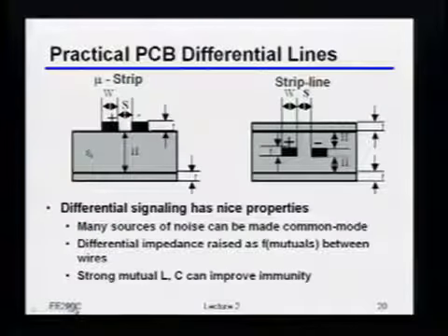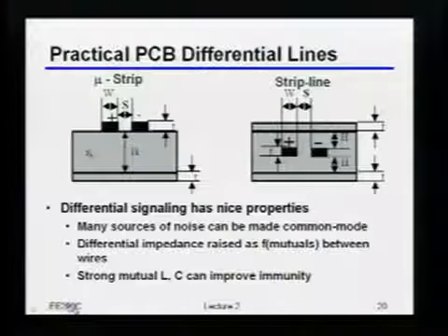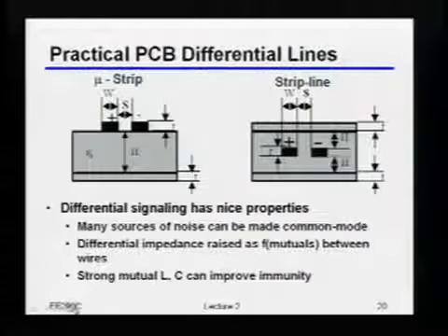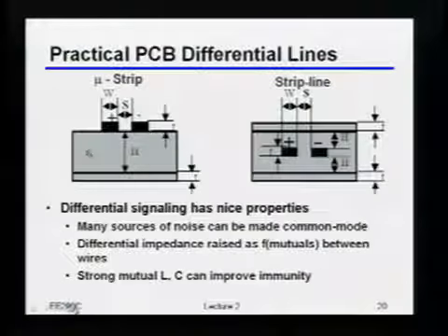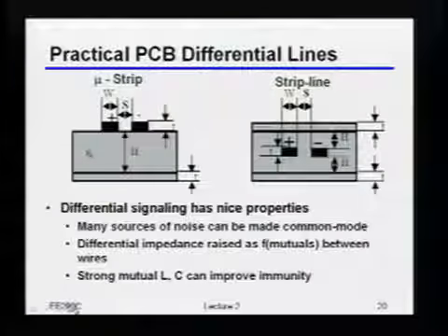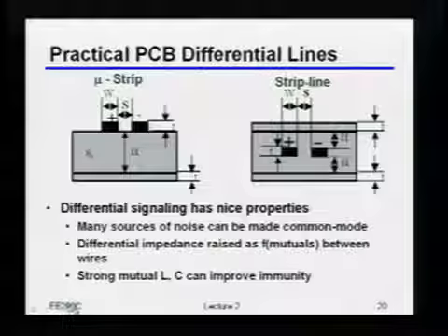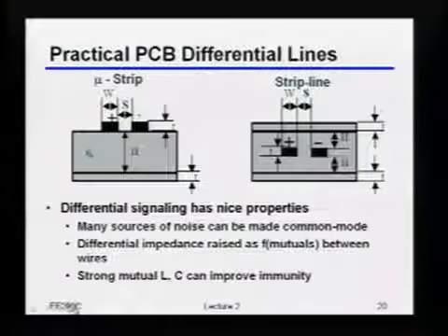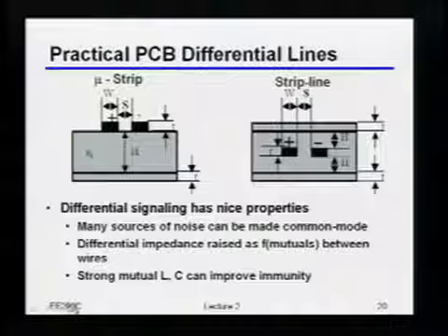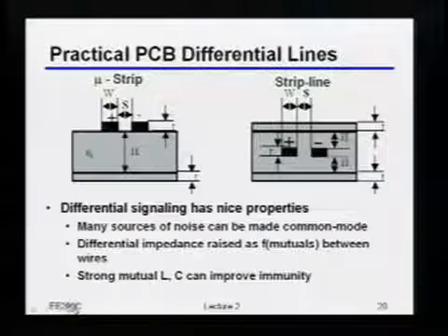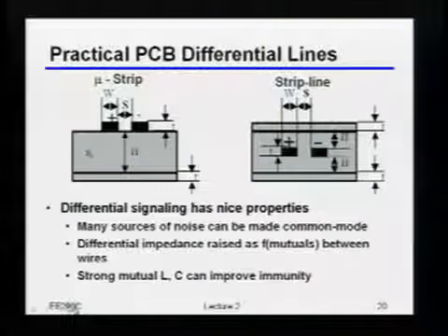Of course, if we look at that backplane, what do these signals usually look like? Typically what you're going to do is some sort of differential signaling. Since I said from the get-go that all of you are supposed to have taken 240, I don't have to spend a lot of time talking about why differential is good. It allows you to reject a lot of the common mode noise, and trust me, in a big backplane with thousands of links and memories and processors, there's all kinds of common mode noise all over the place. So that's good news.